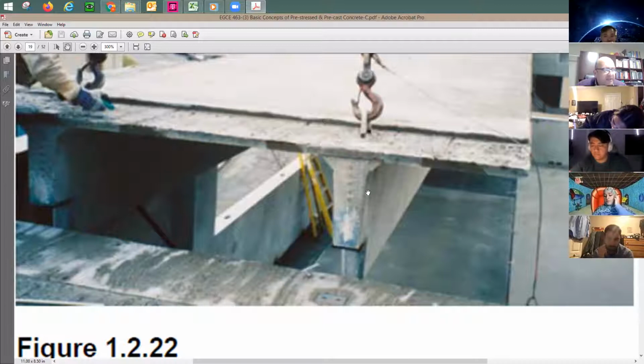We have certain hangers that they attach to the end. So the precasters who produce a flat or straight end of the double T have a kind of hanger here at the top, like this company called Spancrete. But other companies do a notch. A notch gives a little bit more safety and ease of installation. But the other one is easier in the yard. And there's a little, I don't want to say dangerous, but a little uncertainty when it comes to the installation and the hangers.